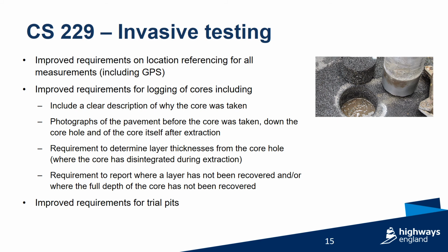There are also improved requirements for test pits, including the reason why the pit has been taken, the traffic direction, the pavement layers, the condition of the material, and where the in situ tests are being completed. These shall be included on the test pit log.